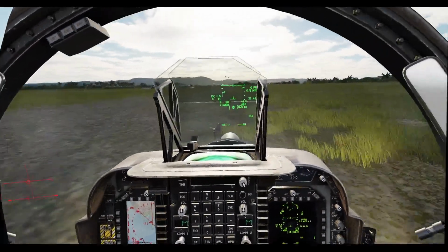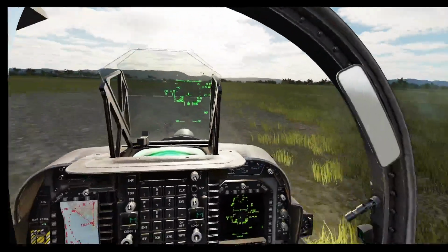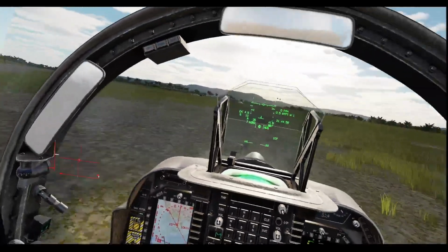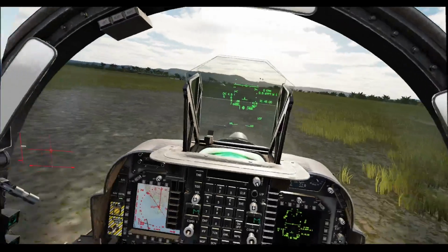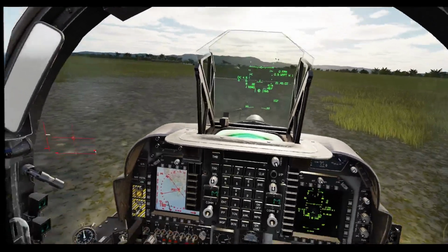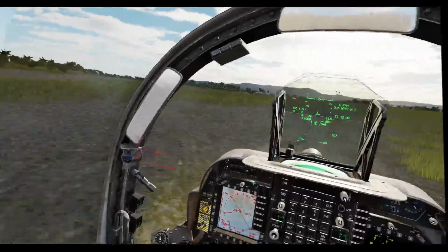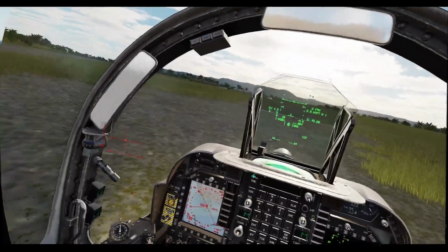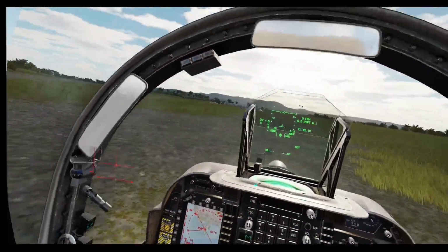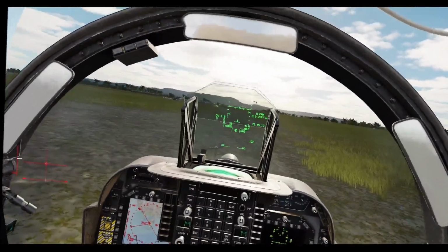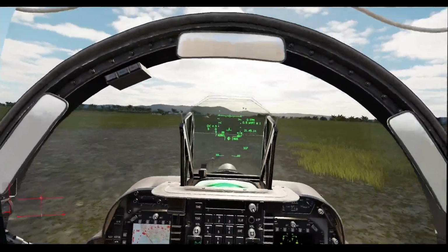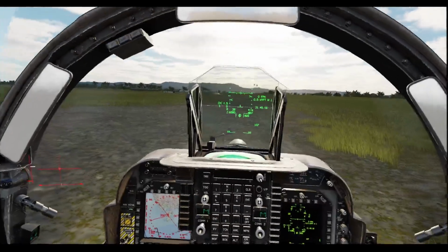Okay, so main things to note. Delta distance between 1 and 1.2, so it's a little bit wider than the other maneuvers, which are obviously 0.8 to 1.0 on the delta distance. Secondly, when you're performing that turn, you might find that you choose to make the first half of the turn a little bit tighter. That's fine. It's more important to make sure that your first half of your turn's tighter than have to overbank on the second half of the finals turn.